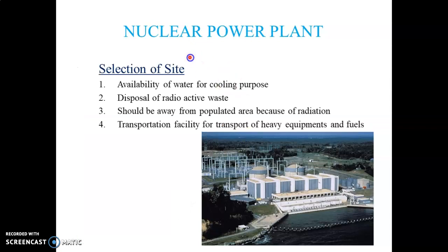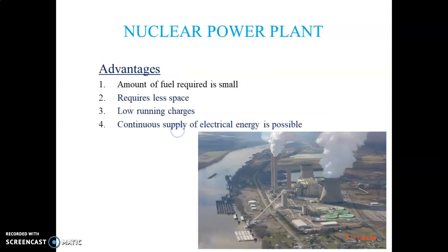Now, the selection of the site of a nuclear power plant. Availability of water, disposal of radioactive waste, it should be located far from populated areas, and transportation facilities are required to transport heavy equipment during the erection of the nuclear power plant.